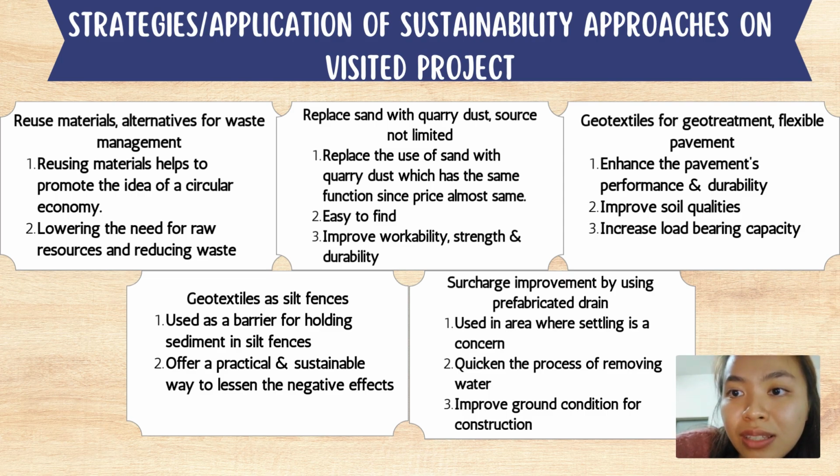The last one is the surcharge improvement by using prefabricated drain. It is used in an area where settling is a concern and can also quicken the process of removing water and improve ground conditions for construction.